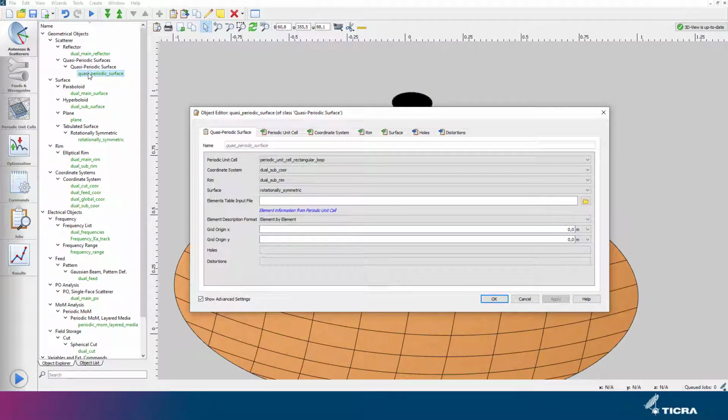Using CUBES, we can adjust the FSS element dimensions element by element, or we can describe the FSS element dimensions using spline functions. For smooth varying quasi-periodic surfaces, e.g. aperiodic FSS, spline functions are preferred as it reduces the number of optimization variables when designing these surfaces. Therefore, we proceed by using spline functions.